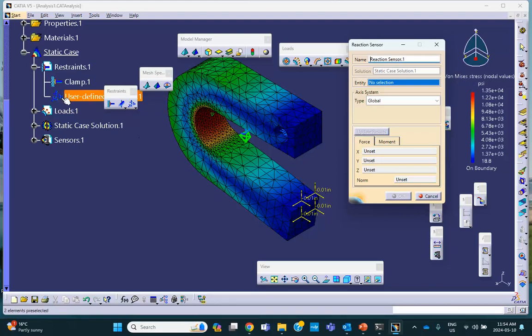It's this thing that I said go down by 0.01. Yes, you select it and you say update, and you're going to get roughly 359 pounds in the downward direction. That is the force. Now, don't say cancel, because if you say cancel, there won't be any record of this that you have done.